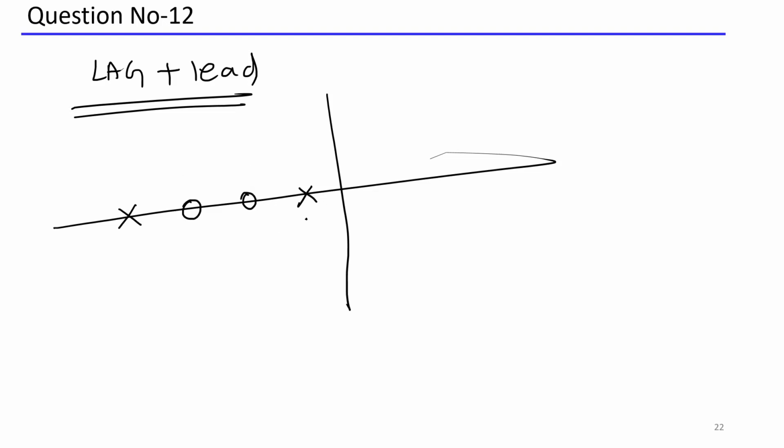If you want to draw the filter characteristics by yourself, you just give some locations: -1, -2, -3, -4. So these two are now contributing a lag. These two are now contributing lead. So this is the lag lead. Don't go from here to here, always go from here to here, left to right, because this is the way we are representing our poles. The pole should always be on the left hand side of the S-plane. That's why, for lag and lead, always draw the one which is close to the origin first, then the lead after that.